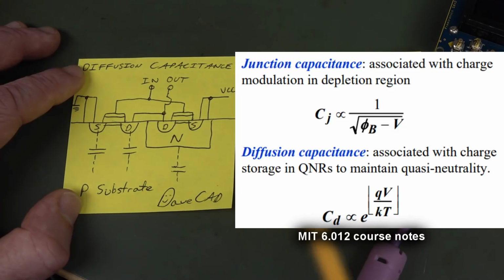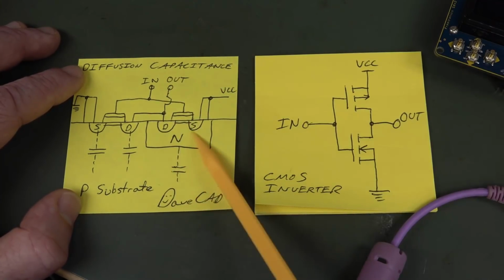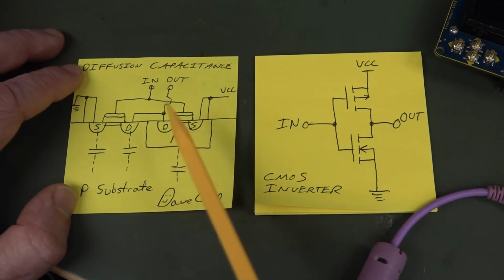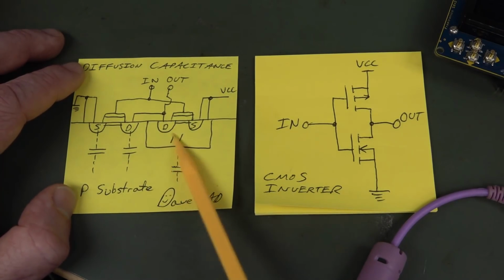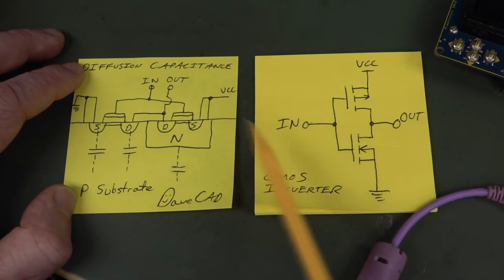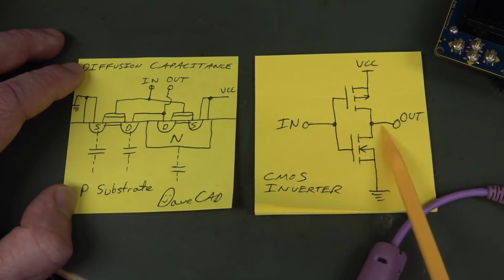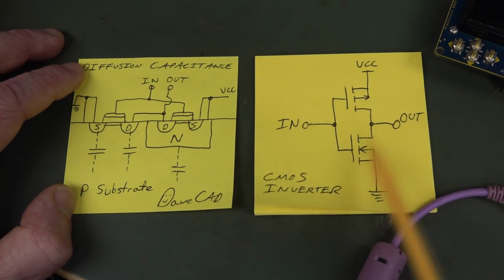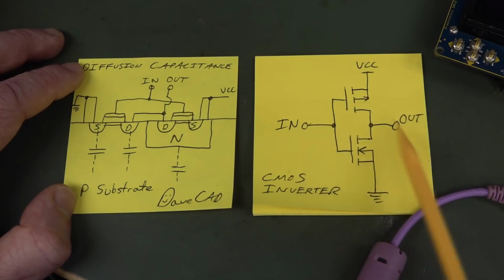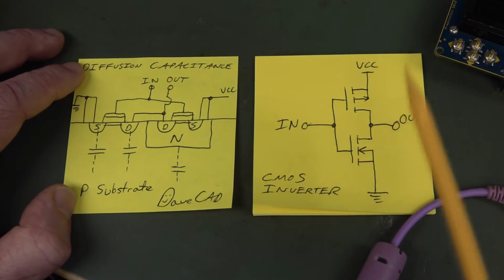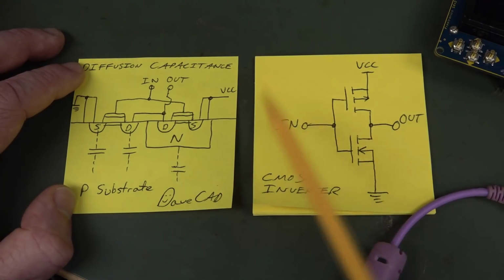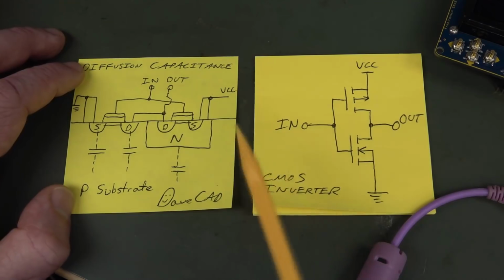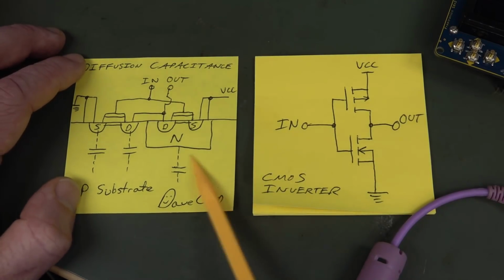So we won't go into details, but another aspect of semiconductors, in particular CMOS processors like you're familiar with. Now, what I've got here is a typical CMOS inverter, and we've got our N-channel transistor and our P-channel here, and that simply forms an inverter. That's how CMOS gates are built, and you get multiple ones to create AND and NAND and NOR and XNOR gates and everything else that makes up your familiar microcontroller these days.